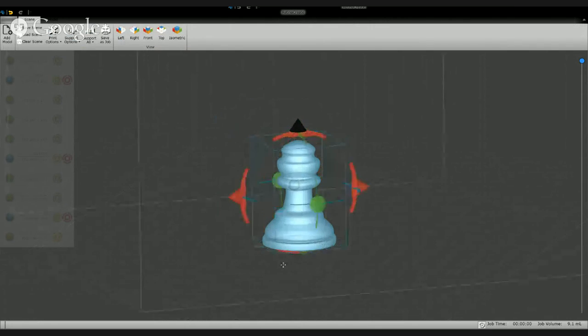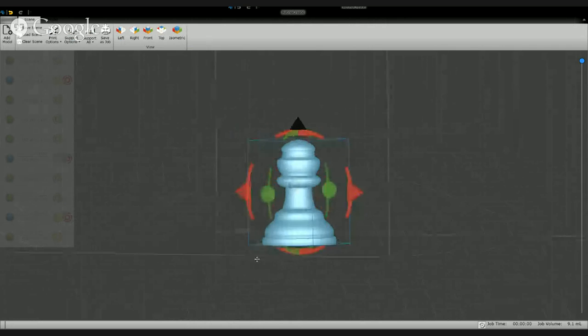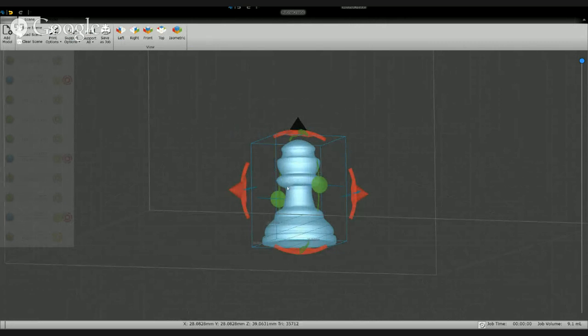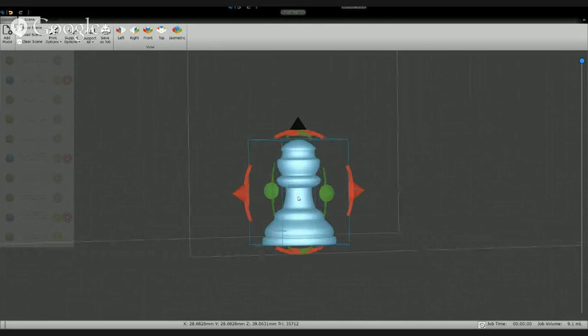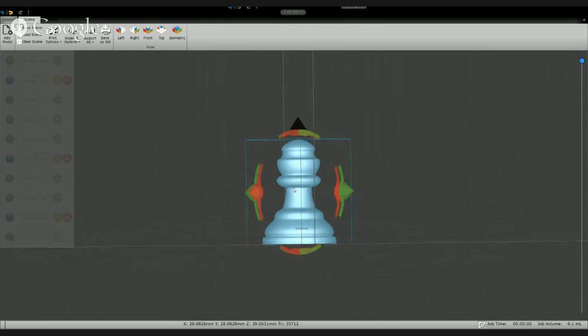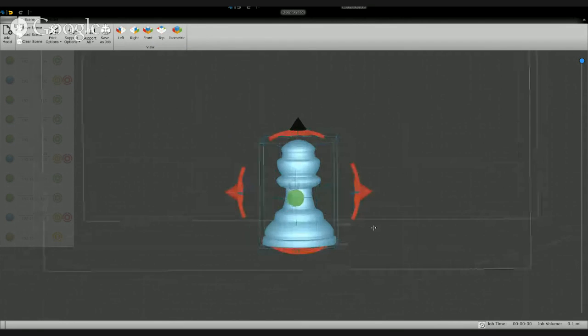And then nothing juts out terribly much. This here juts out horizontally enough that with an FDM printer it would probably fail there because the angle's too steep. It would produce a lot of stringy material that sticks out here. But in an SLA printer, probably the main advantage is the high resolution, but another great advantage is that you can have these horizontal juts for a little bit and it's okay. So with a model like this, you could potentially print it directly on the build plate as is.